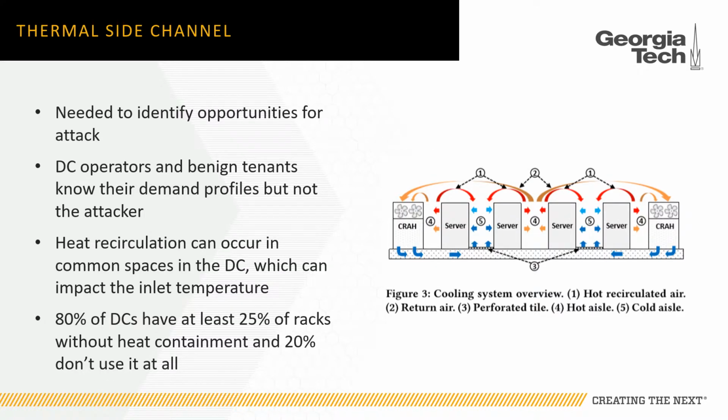Now, what happens in reality is that not all of the cold air is utilized, and at the same time, not all of the hot air is captured by the air handling units. And what you have is some of that hot air will flow back into the cold air aisle through the common space at the top of the data center or the top of the rack space.